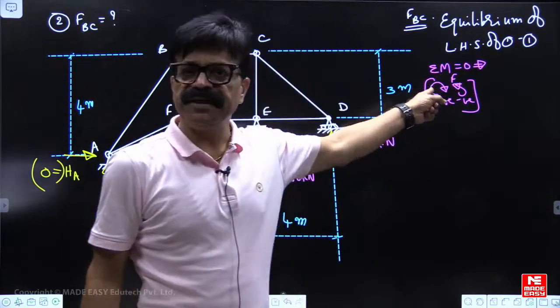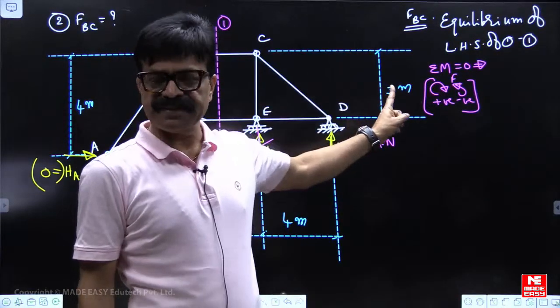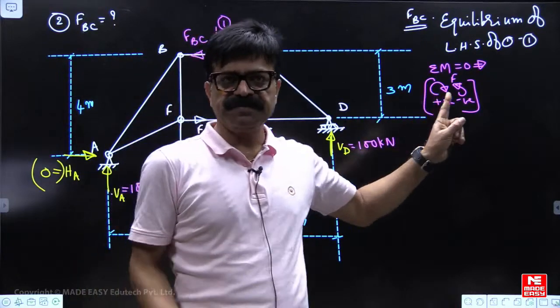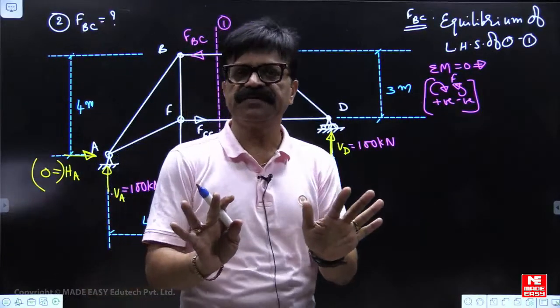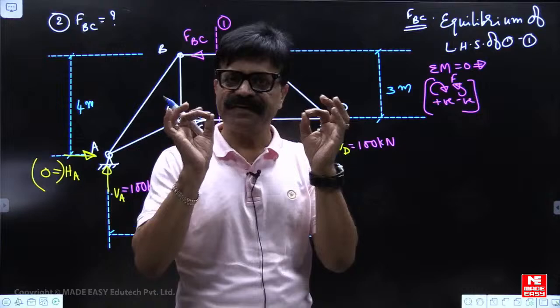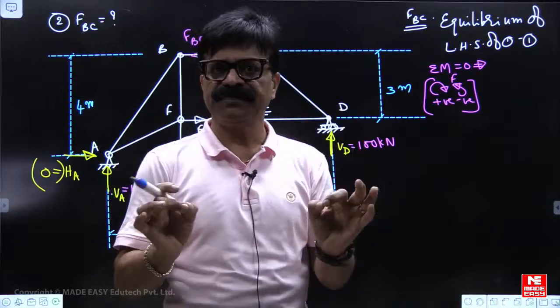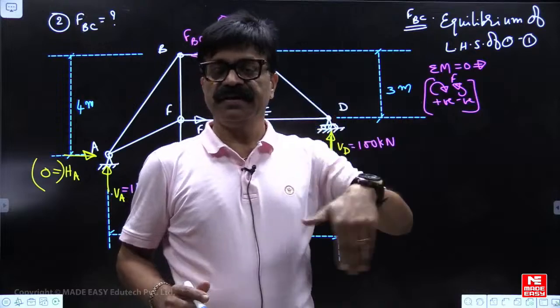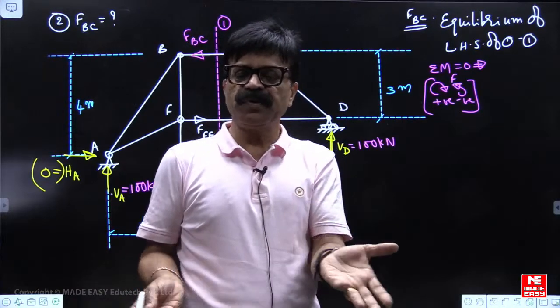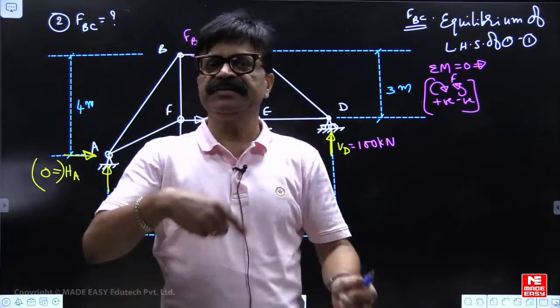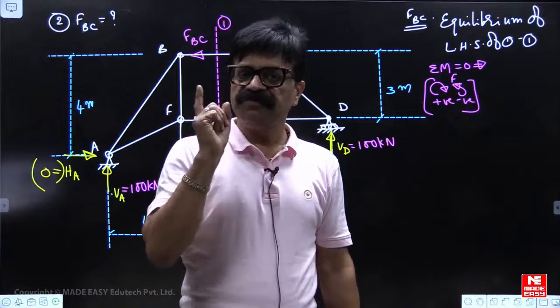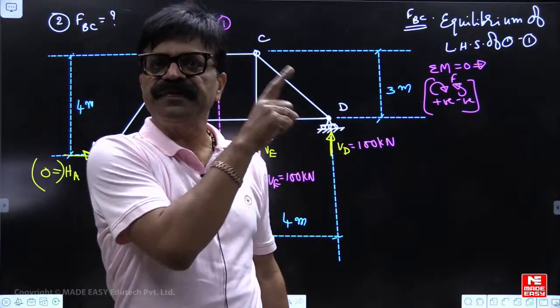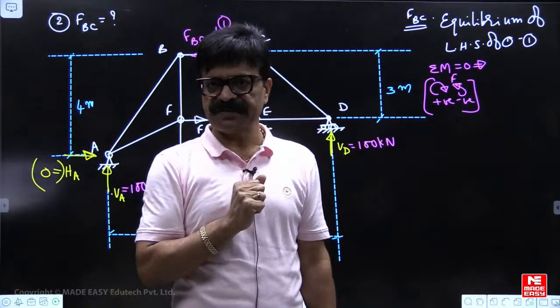This is not a bending moment equation, this is an equilibrium equation. Equilibrium equations deal with only the external effects of the forces, meaning whether it is in equilibrium or not. If not in equilibrium, with what acceleration it translates or rotates. The internal bending moment equation means what that moment is doing. Is it bending or twisting? When you are writing the bending moment equation, you are writing the internal effects of the moment.